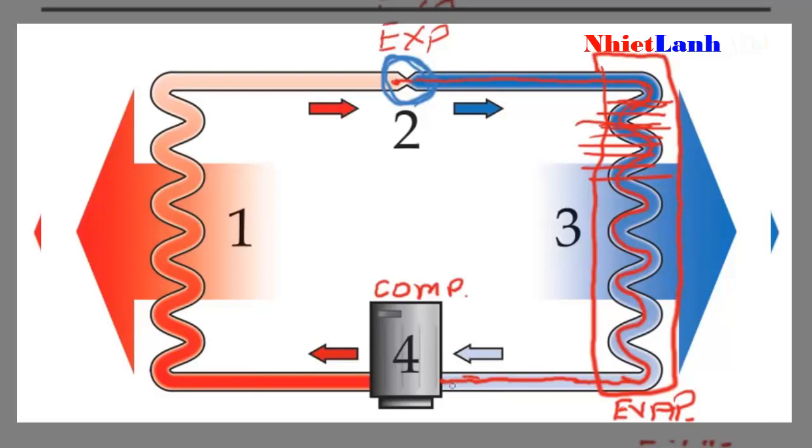So the pump is sucking this gas in, and what the compressor or pump does is it compresses or pumps this gas up into a high pressure gas, and this high pressure gas picks up heat as it goes through the compressor and comes out through this copper line and enters what we call the condenser coil.